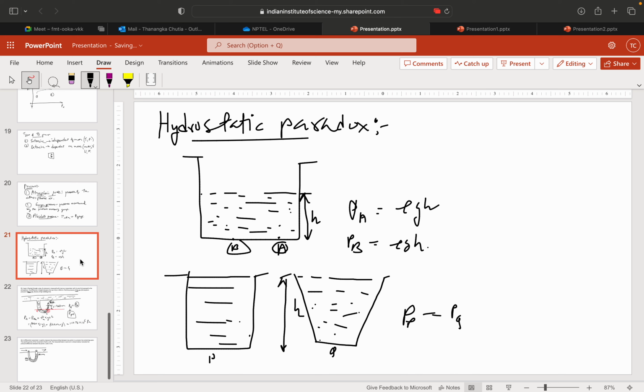Now, in order to solve problems for calculating the pressures of a flowing gas or a flowing liquid, you have to understand what the hydrostatic paradox is. The hydrostatic paradox says that I don't need anything to measure the pressure at a point A if points A, B, C are at the same vertical height, and I know the height from the level from where I want to measure.